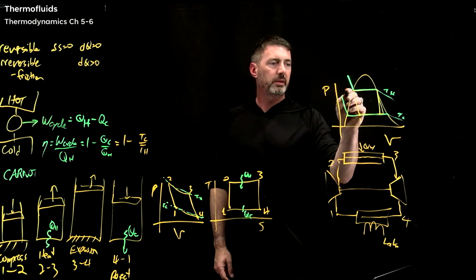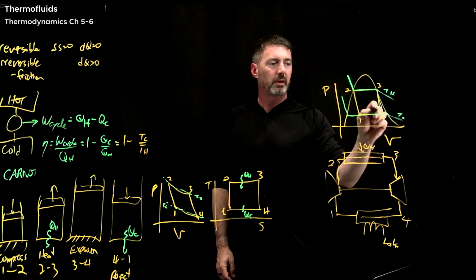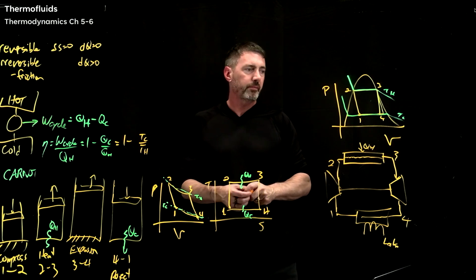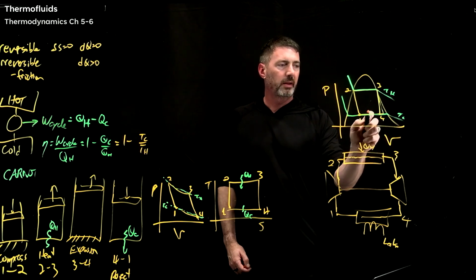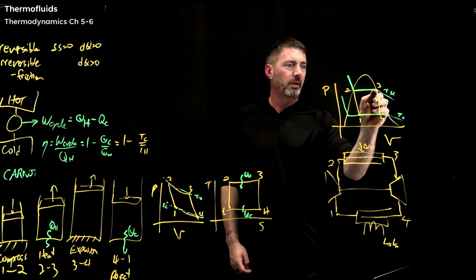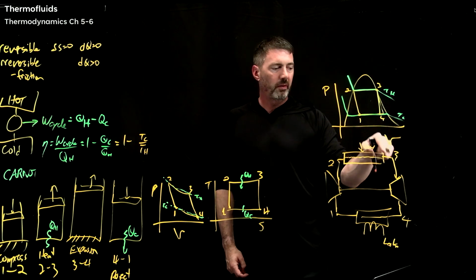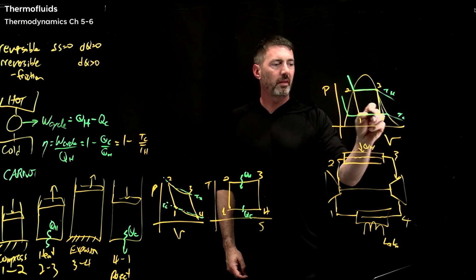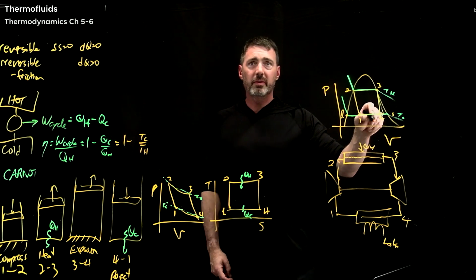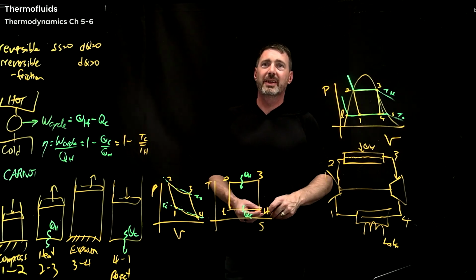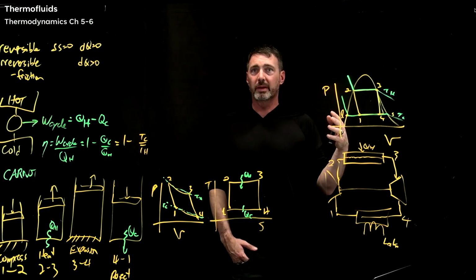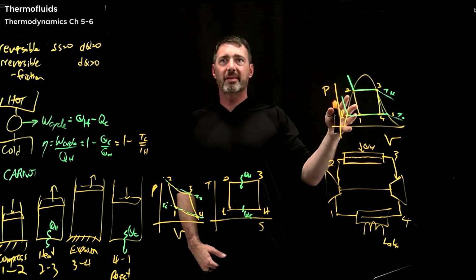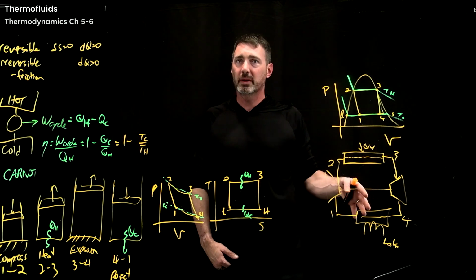And so again, this is 1, 2, 3, 4. If you're actually going to make this Carnot, the biggest problems happen right here. I want you to think about that. Let's look at the turbine first, going from 3 to 4. This is starting with vapor, but as soon as I start going over my turbine, I'm picking up little bits of liquid, because this is where everything is liquid, this is where everything is a gas. And so my turbine is then having little bits of droplets of water slam into it. And so you can't build a system because that turbine just gets completely destroyed, okay?